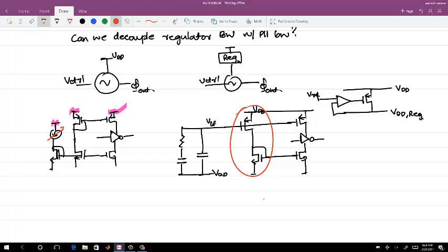Swing at loop filter output? No, let's say that in a locked steady state, only small ripples will be there. Let's not bring those ripples in right now. So in steady state, the voltage is constant. It only changes when you change the frequency. Any trade-off?